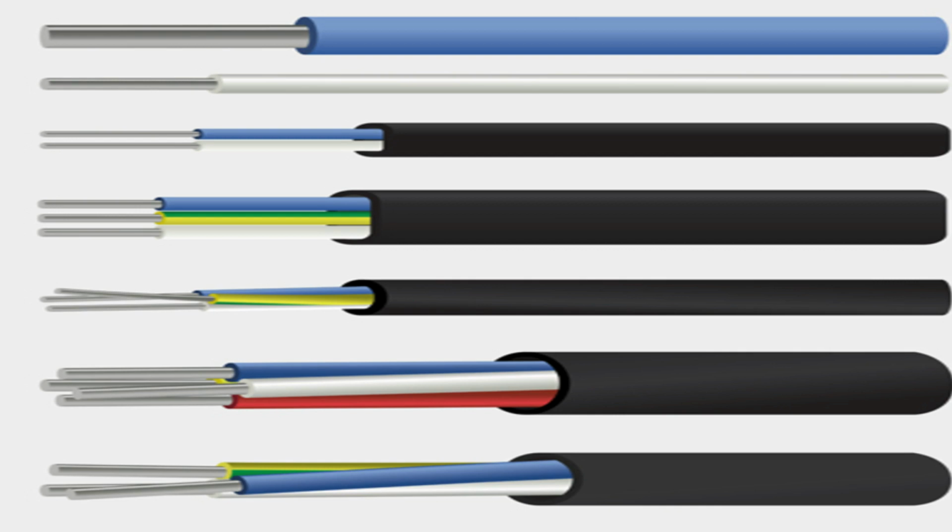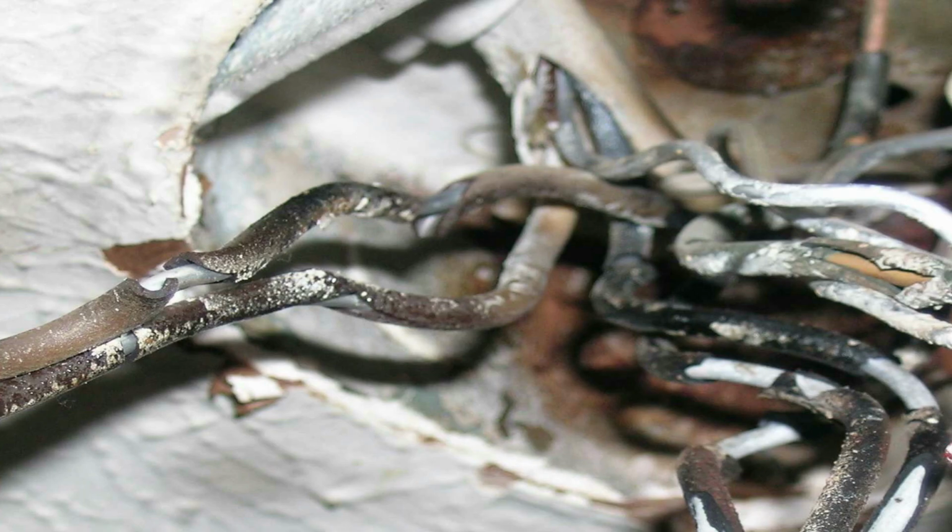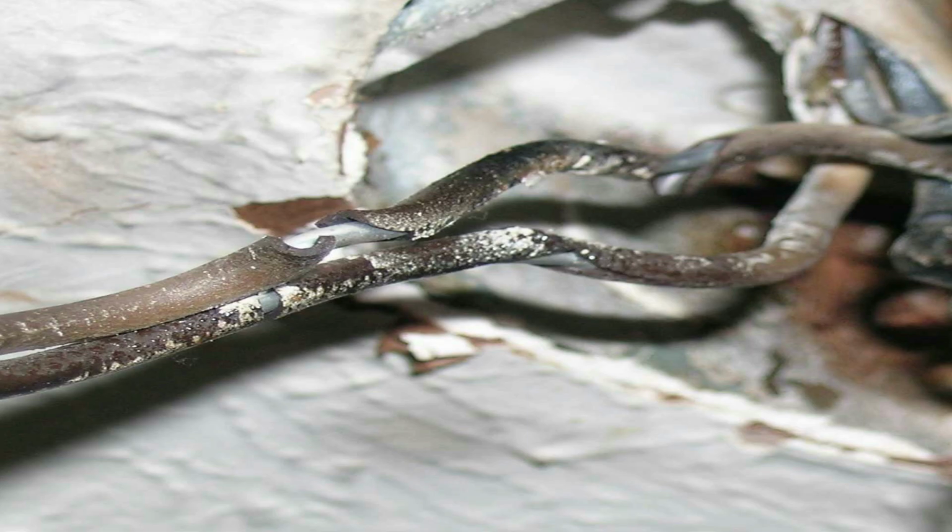The oxidation effect of aluminum occurs when an aluminum cable, particularly the cable ends, is exposed to air. A resistant oxide coating will be formed at that end, which makes contacting difficult and thus increases the cable's temperature.